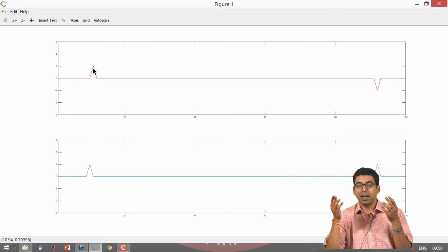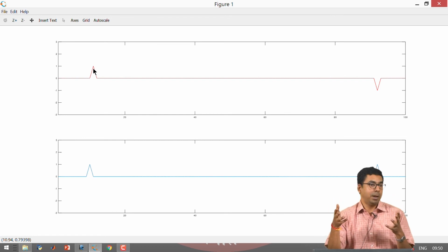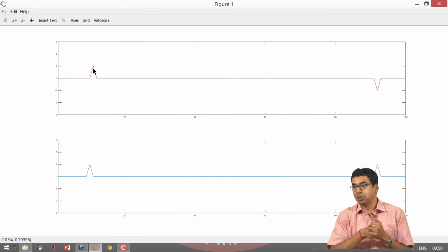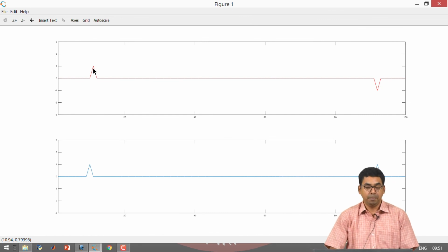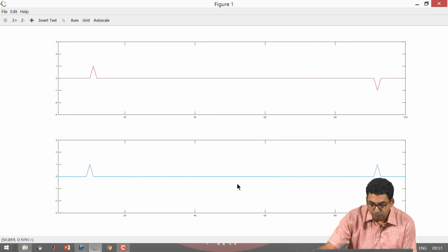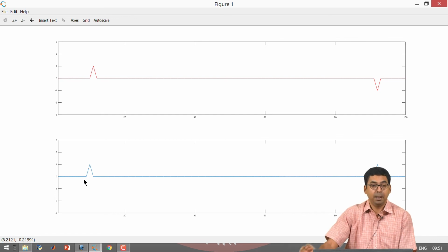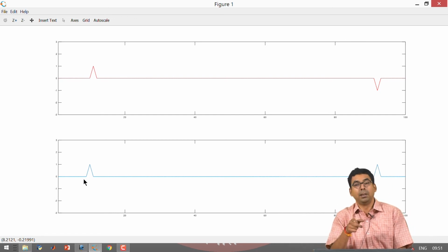So, I think in our mind we are starting to already figure out where we are going. We are trying to understand the term reflection coefficients, right. The reflection coefficient is going to be having a magnitude and also going to be having a sign is what we are indirectly saying. Same way, if you look at the bottom graph for current, the current actually did not flip on the right side, but it flipped on the left side. So, something is happening. So, when the voltage flips, the current does not flip. When the current flips, the voltage does not flip.